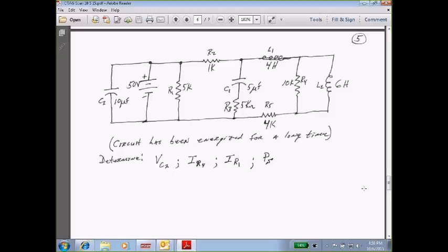Now, during that time, there would be some resistance in L2, at which then we would have some current through R4 and some through L2 until L2 becomes 0 resistance. At that point, then all of the current goes through L2 and none of it through R4. And that's an exponential function, which would occur in just a few seconds or milliseconds, whatever our time constant figured out to be.